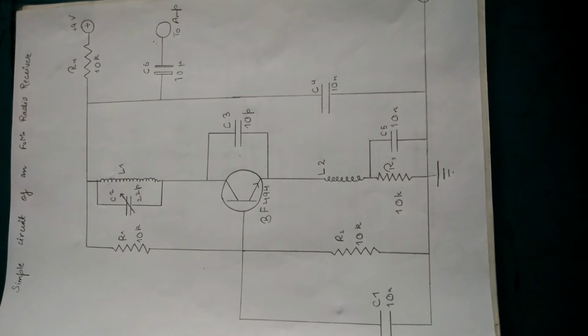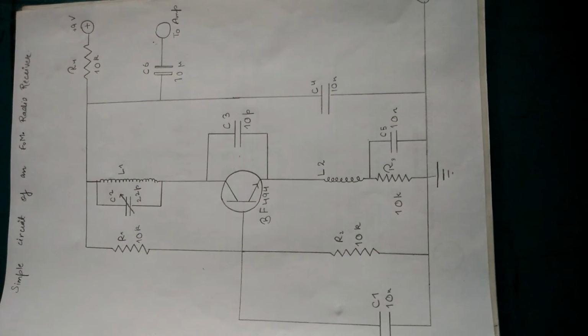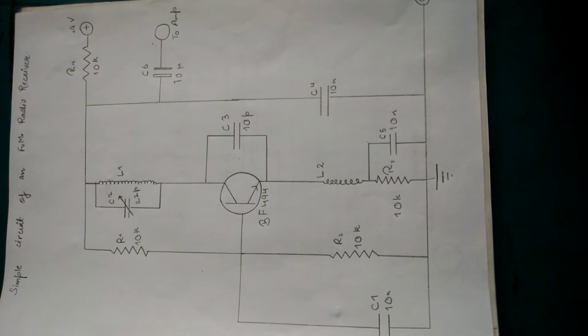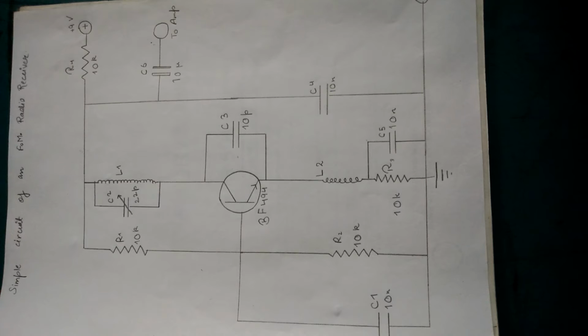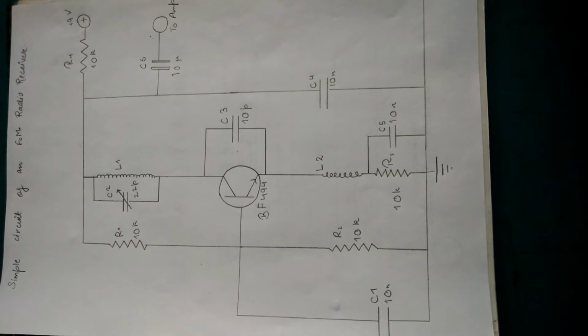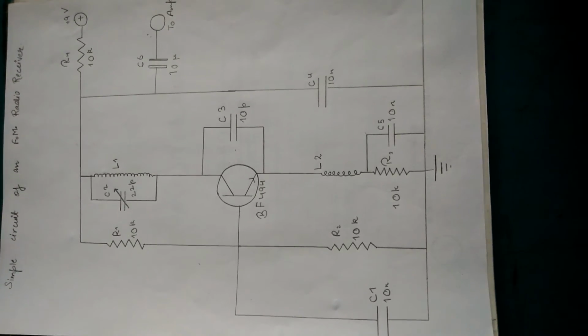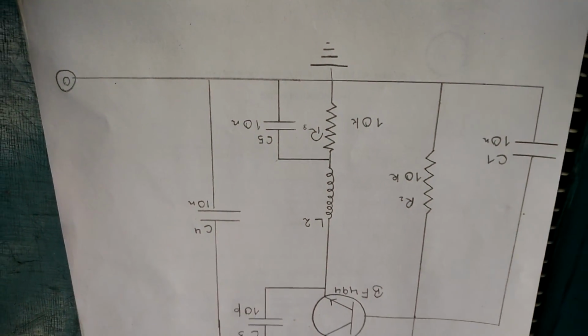Each time the circuit flips across the above on and off states results in a significant stepping up of the amplitude, which in turn constitutes greater amplification of the received signals. The procedure also gives rise to noise, but only as long as a station is not being detected. The above design has one drawback, though: the output received from the circuit would have a greater content of sawtooth noise compared to the actual FM reception.